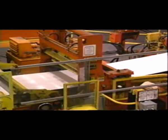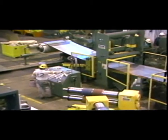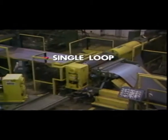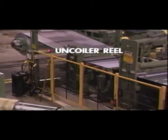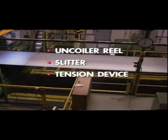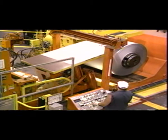Slitting is a common process in the coil processing industry and is a shearing process in which wide coiled stock is slit into multiple narrower coils. Slitting is accomplished using a slitting line, of which there are 3 basic types: the single loop, the double loop, and the pull-through. These slitting lines consist of an uncoiler or payoff reel, a slitter, a tension device, and a recoiler.